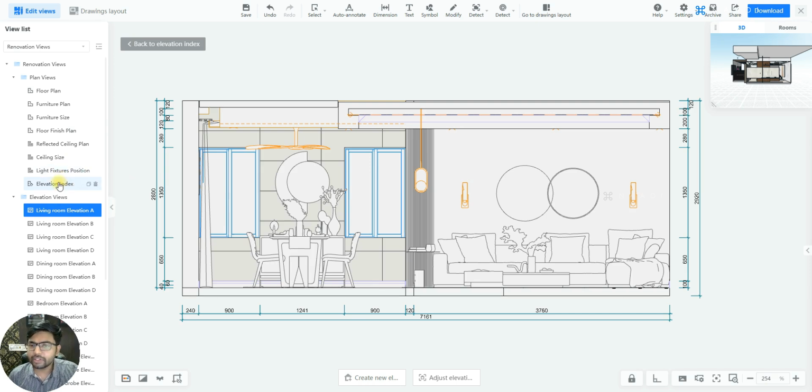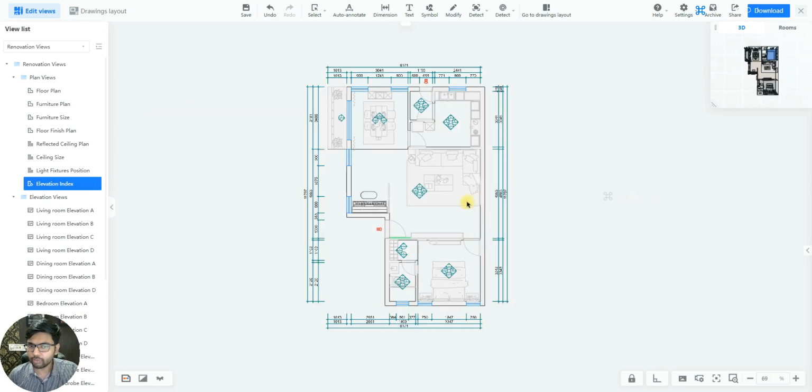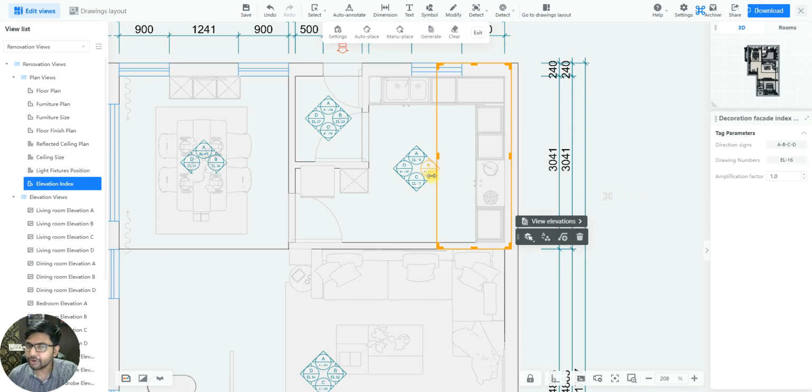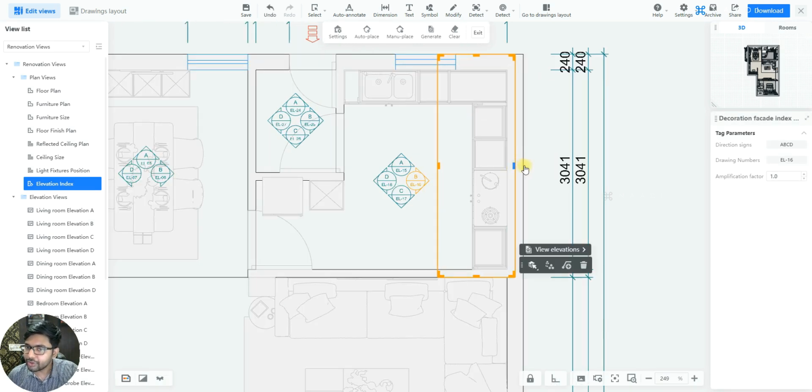And now you might be having this question. The same wall elevation what we took for the living here might also apply for your kitchen space, right? So I could even generate the elevation for your kitchen spaces using your construction drawing itself, right? In that case, why do I need to go to custom furniture drawing to generate the elevation for your cabinets? I could generate it in construction drawing itself, right? The thing is, yes, you can generate your elevation drawings for your cabinets in your construction drawing itself. The difference lies in detail.